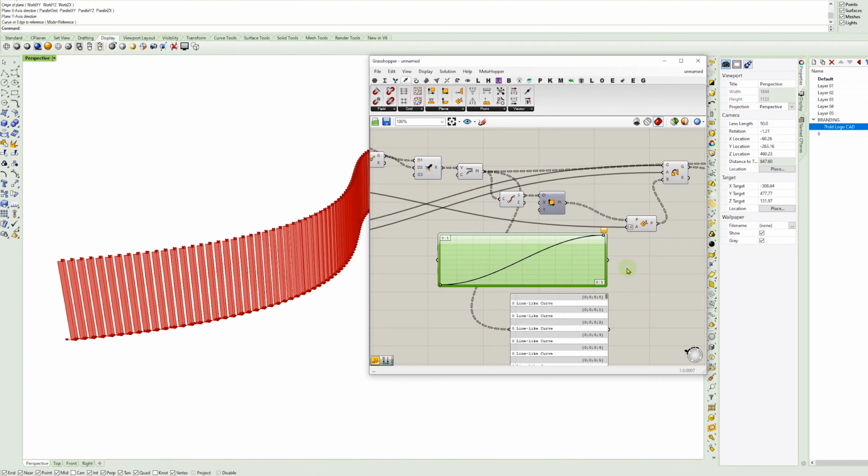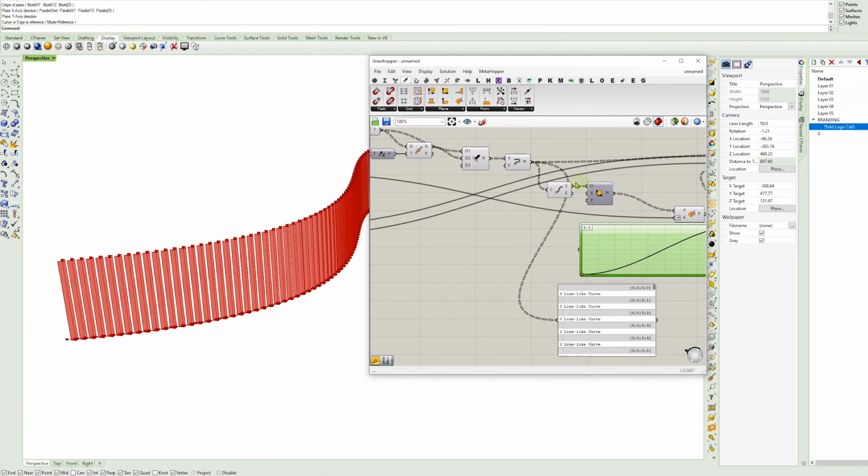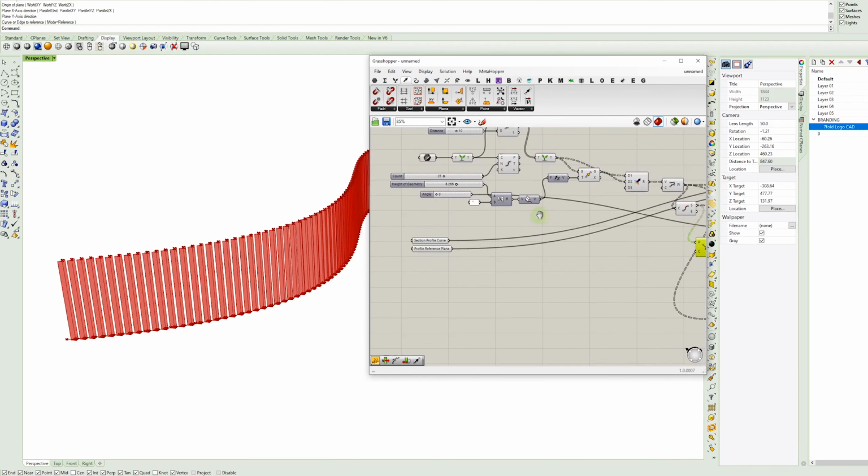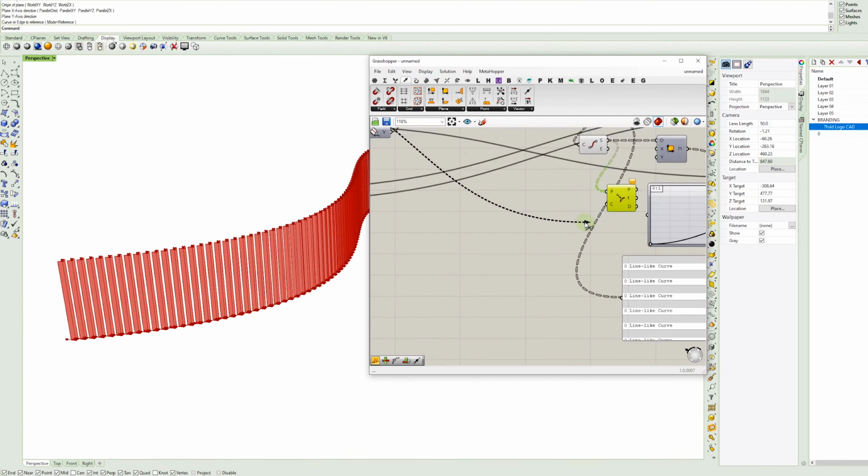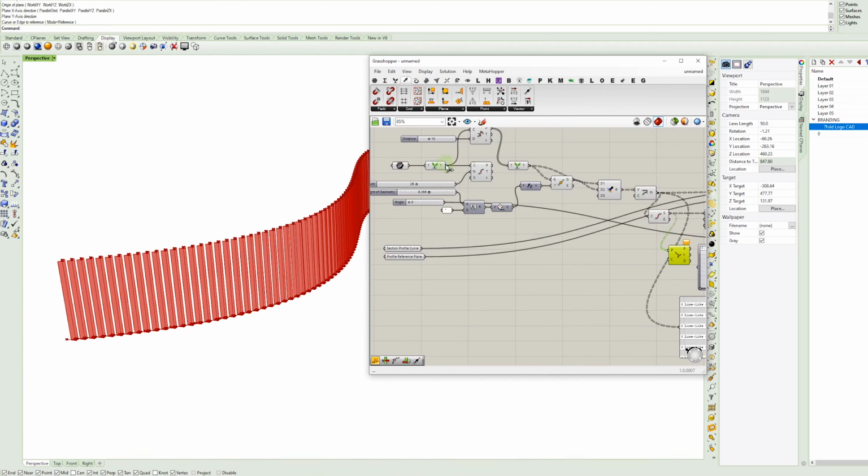And then what I'm going to do is take the origin points I'm using for my planes, and I'm going to pull those. Let's just do CP. So typing in CP, going up to curve closest point, and then pulling this point, my start point, to the original curve. And let's actually do it from the grafted curve.